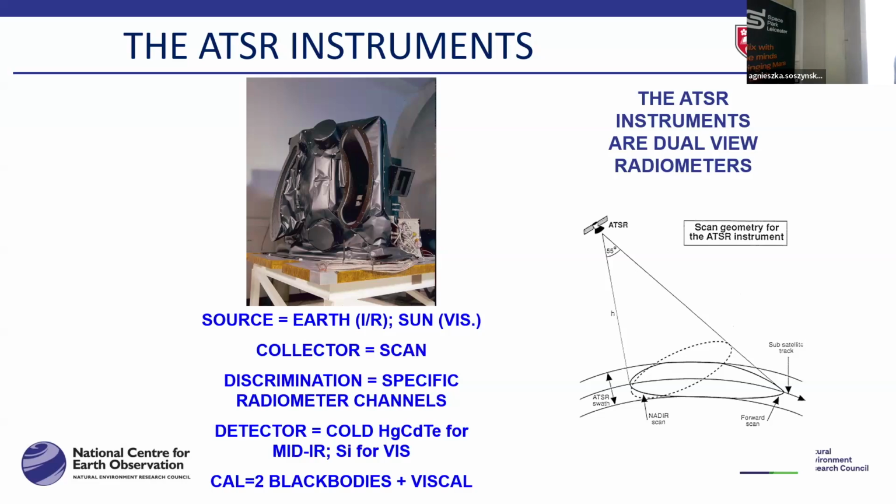You need some detectors. The quality of detectors ultimately really does influence the quality of data that you're going to get out. We typically use mercury cadmium telluride in the mid-infrared. And then calibration, so it's right at the bottom, which means it's fallen off most people's viewpoint, which is about where calibration ranks quite often. If you talk to Dave, calibration is the only thing that matters. I'm not sure you disagree with that.